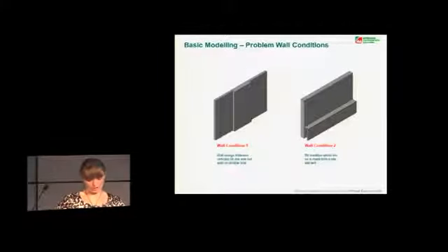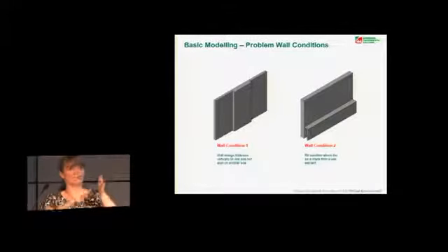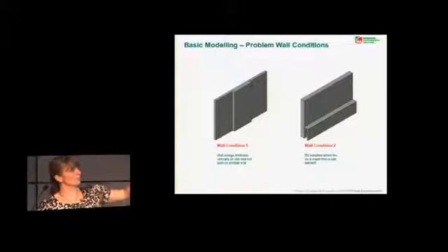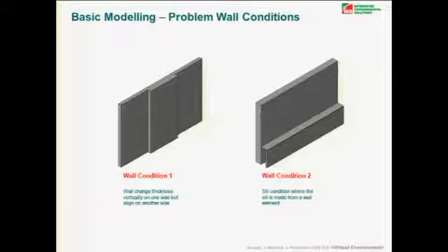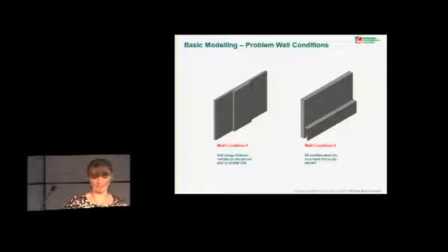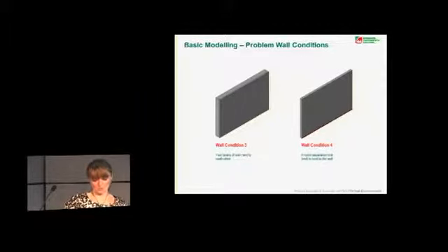Same sort of idea, same rule for what we call jogs. So a wall, but part of it actually kicks into the room. Two examples there: one is the sill condition, and one is a thicker wall in part of that wall. What our software will see is, if the sill, for example, is set to be room bounding, our software will actually take the line of that sill as the wall, and it will then make the external wall a shading element. Okay, so you don't really want that, and it would cover up any windows that were in there. So just by setting the vertical and the horizontal of the sill to be non-room bounding, it will then go back to the line of the wall, and that's what you want. The same principle applies here: just set the wall to be the room bounding element and the bit that kicks in to be non-room bounding. Michelle's going to go through all this in more detail than me.